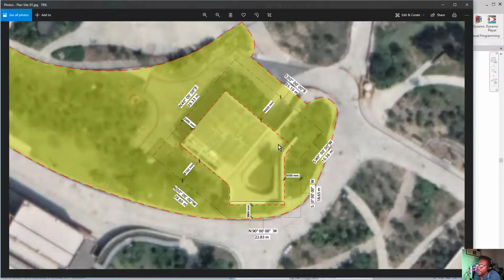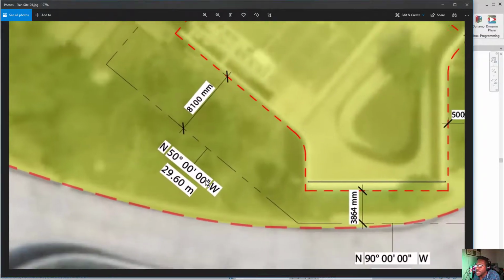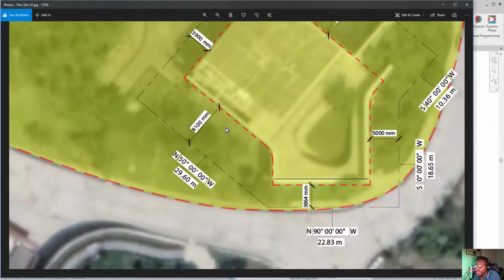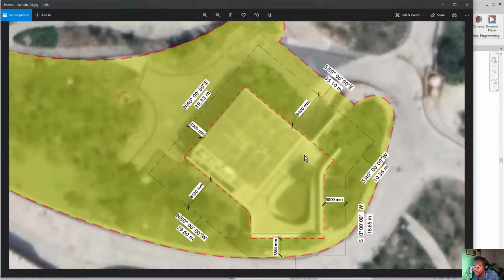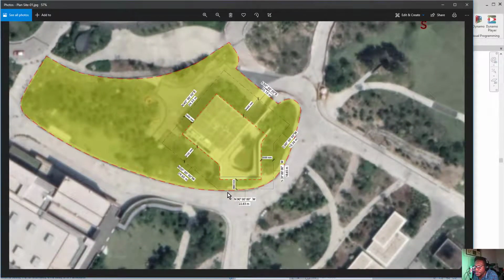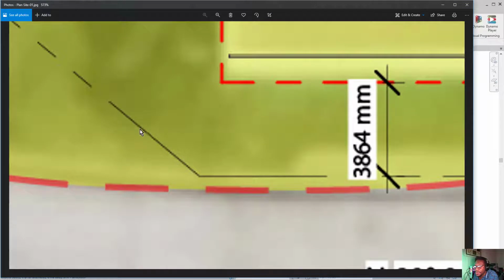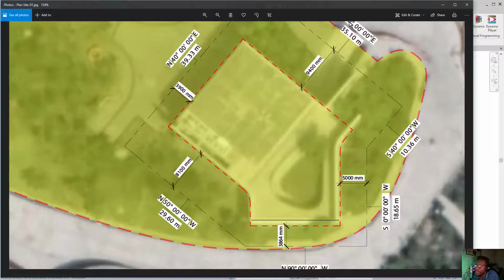You can see where the building will go. And then you can see the site boundaries that's here. Now for each of these site boundaries, it actually has the exact longitudinal, latitudinal values and angles, which you can input directly in the program, and it will give us the exact drawing here. Now it's important that we input these values and we don't carry this site plan into Revit and trace it, because this is an image, and we will never be able to trace this 100% if we try to visually trace a line here. So instead, what we should do is input this data manually.